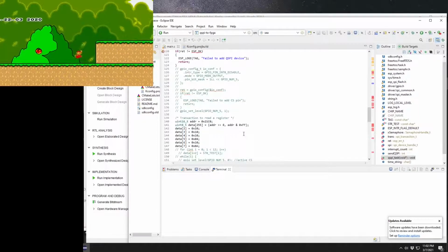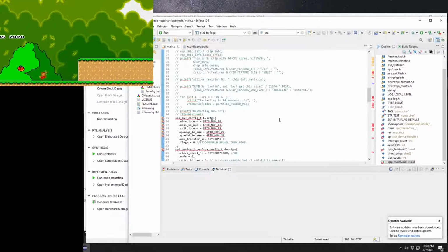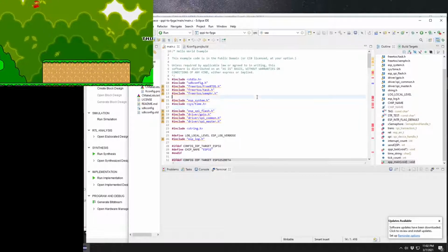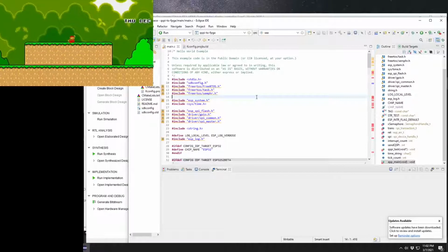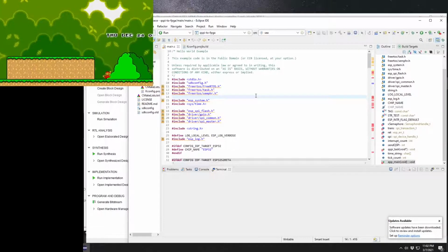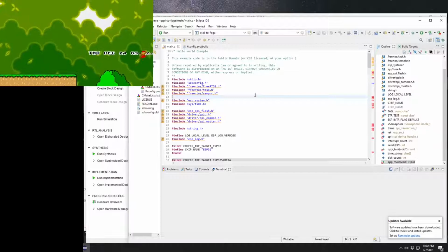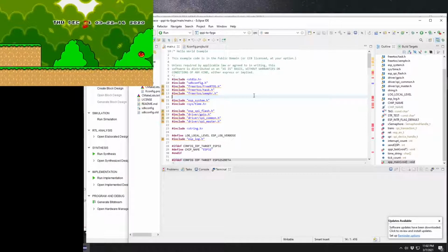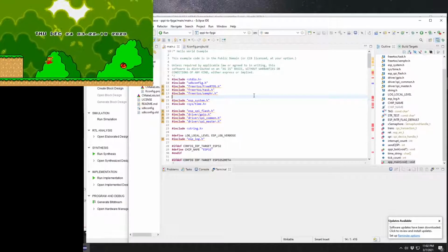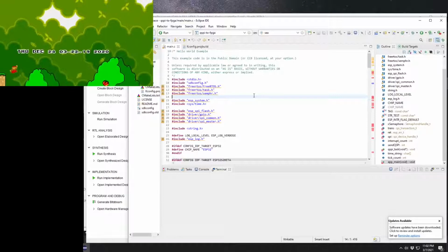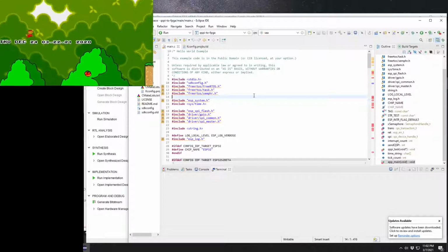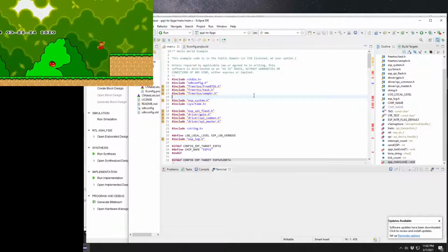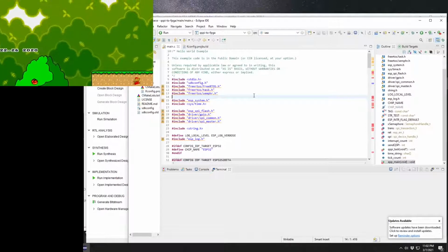And I think that if I take some time later, I can port some of the required functions, or make some of these required functions available within the Arduino environment. But basically, the reason why I was doing this with the ESP IDF is because it's not easy to use this QSPI peripheral. Honestly, even the documentation about QSPI for the ESP32 is not great. It's mostly focused on using the protocol to read and write data to flash memory, and connecting to specific brands of flash chips and things like that. And that's not what we're doing here.